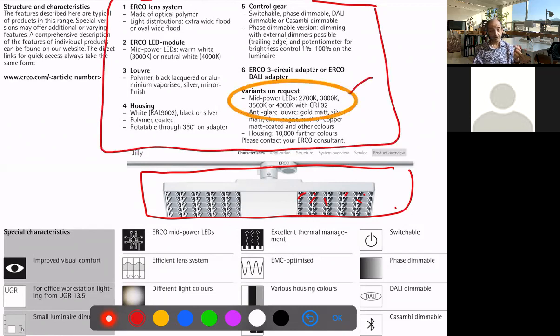So you know the range of color temperature they give you, from really warm to cold lights. This is the usual range we can buy. You see that the UGR, the glare ratio, is really low, it's 13.5, which is almost near ideal. You know that it's EMC optimized, so it will not create interference with the electromagnetic waves. Be suspect of that also, and if that is the case, be very careful with substitution and changing individual lamps.